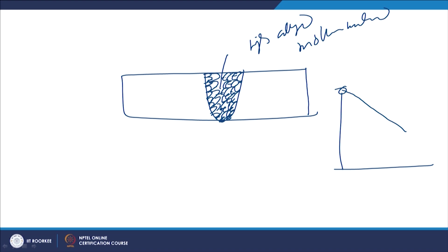So, this in turn subsequently leads to the development of the solidification crack, and this is happening primarily due to the presence of excess alloying elements at the weld center line, and the same is also the reason for the liquefaction cracking, where a lot of chemical heterogeneity exists at the grain boundaries, leading to the wider solidification temperature ranges, even in the heat affected zone, increasing the liquefaction cracking.